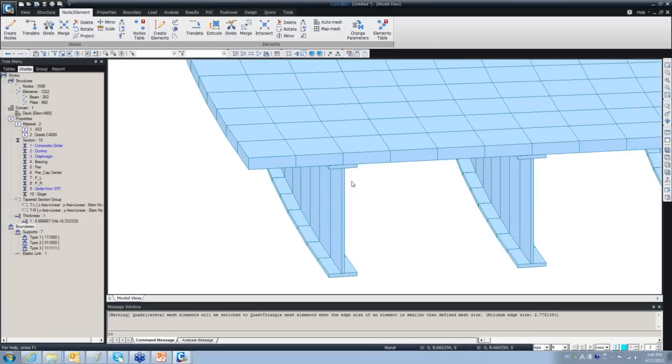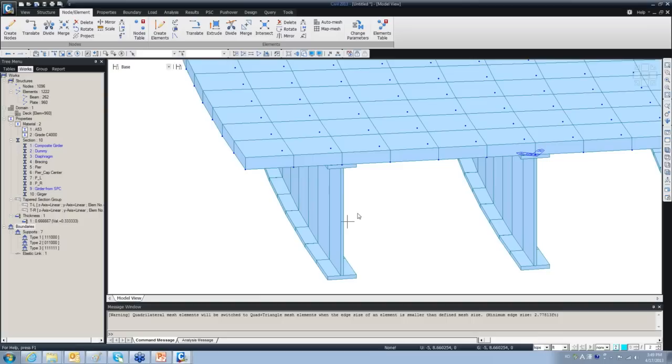So there is just one other point important here. You remember I talked about that offset option. The offset option is helpful here because for the plate I push the node to the bottom, so it's just exactly placing right in the bottom of the slab, and then for the girder I pushed it upward, so they are sharing this node, so you don't need to define any additional rigid links to make this connection.